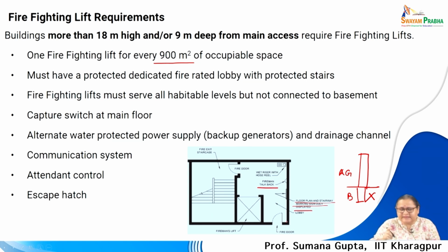So, fireman's lift is not necessarily one lift, but it is an enclosure having a lift, having a staircase, having a firefighting system within it, also communicated with the address system and connected with the emergency power supplies. Also, it should have an escape hatch.